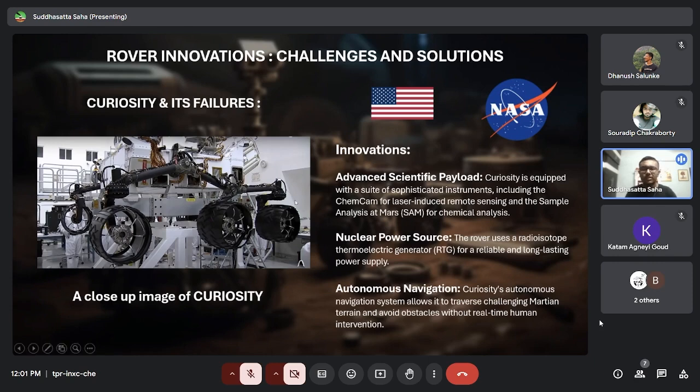It is of the order of a few hundred watts or so, but it is very efficient in driving these operations. You might ask why not use solar panels, because this nuclear power source seems a very expensive affair, with a high maintenance cost and a high one time deployment cost, but it is very much durable and resistant to wear and tear. This is the kind of generator which has no moving part at all. So all those problems associated with objects having moving parts are avoided, unlike the normal generator you see in your home, which has a lot of moving parts.